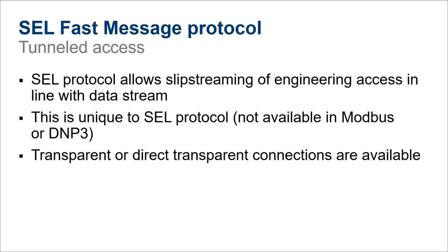So that was the basics of SEL fast message protocol. It's a pre-configured protocol that defines all data available in fast message when the client and server connection is first made. There's a lot of overhead with this protocol, but it's very easy to configure, very easy to set up. You just select the tags you want to find.